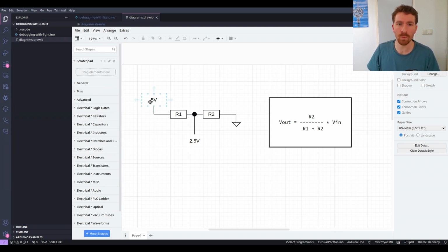And it's going to be somewhere between what went in and 0 volts down here on ground. Now, in the case that you have 2 equal resistors, what you should see is exactly half the voltage. Of course, you have to account for the fact that components aren't perfect, and you might not see exactly half. But you're going to see something very close to half the voltage that went in.